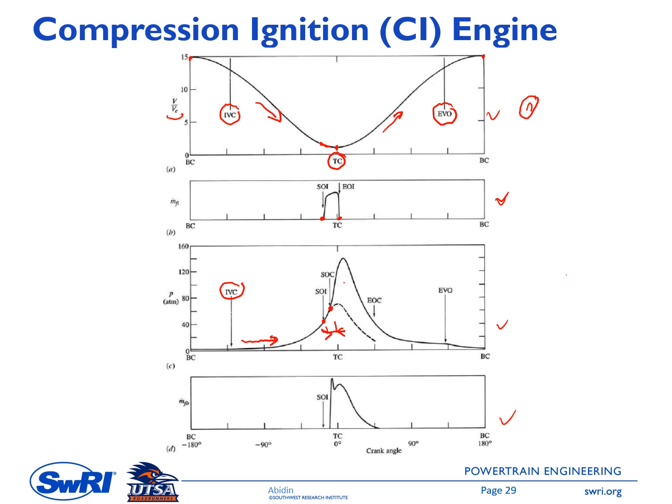And then there'll be a combustion process, and then at some point the exhaust valve opens, there'll be a blowdown process. This one is end of combustion, EOC, sorry, and this one is EVO. So EVO here is exhaust valve open. It means here there'll be a blowdown process from this EVO to BC. And then if you don't have a combustion, then you will have a motoring pressure. It is shown here as the dash line. So this one is the motoring pressure.